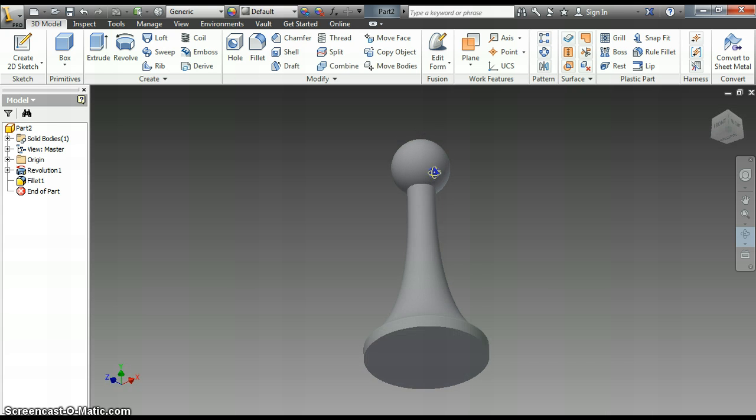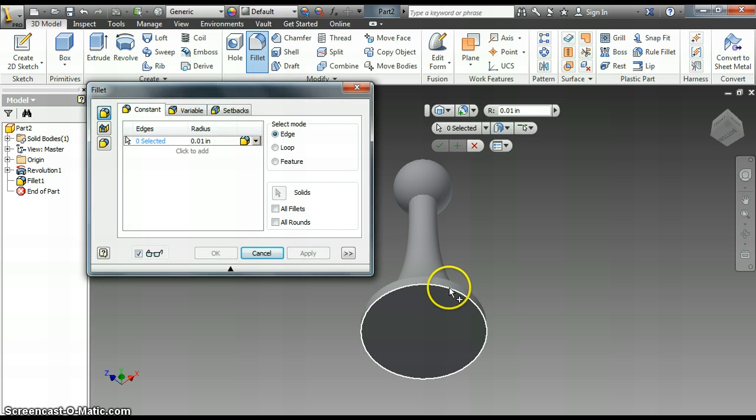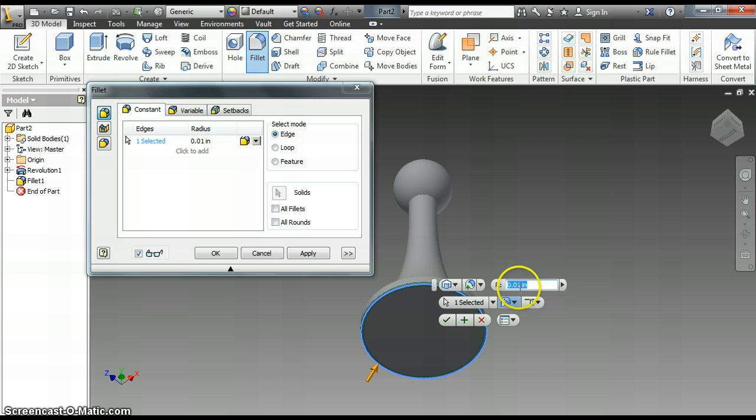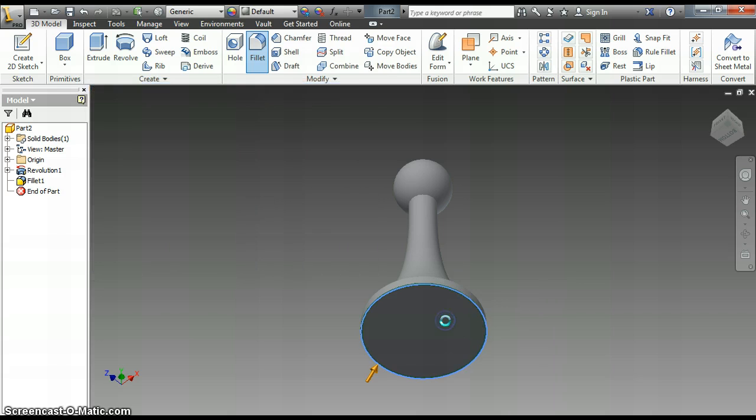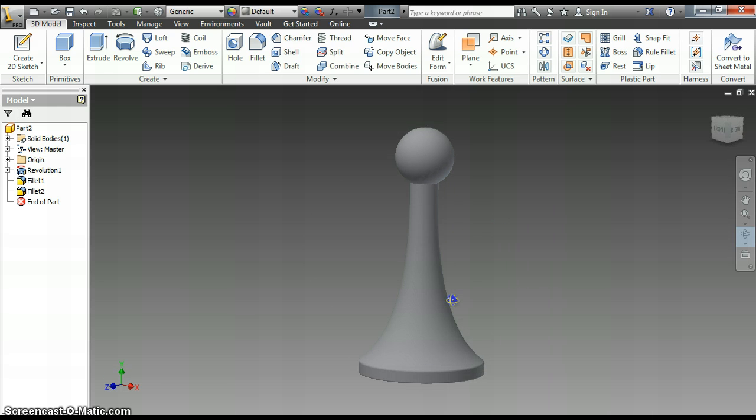We're going to do the same thing with the bottom. We're going to fillet that. Fillet this edge. 0.01 should do the trick, except that we're going to be laying this on a flat thing, so I might half that. So instead of 0.01, I might go 0.005. Check that. It'll still lay flat, but no sharp pieces on it. So we've got a nice piece here, rounded edges.